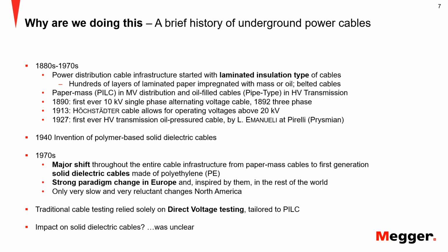And the interesting thing here is that all the testing methods were tailored to the oil cables, to the paper cables. And the question was, is that even applicable to solid dielectric cables, to extruded cables? And the answer later found by the scientists was no, it's not. And that was one of the aspects why certain testing technologies emerged.